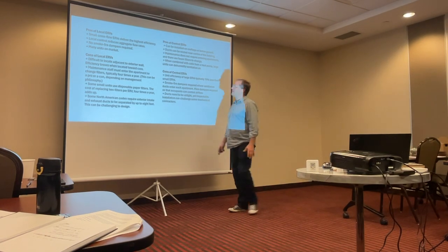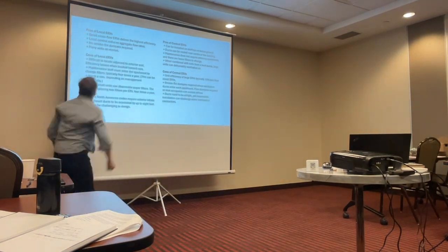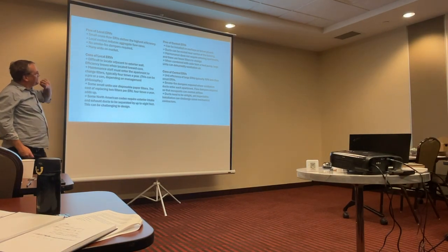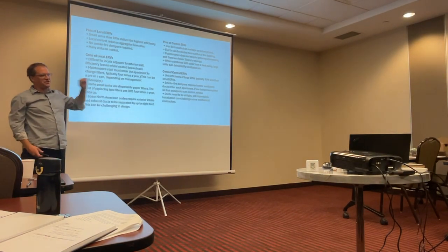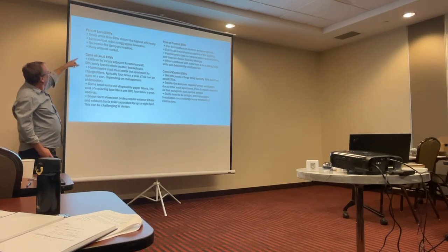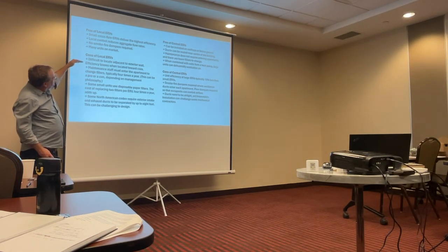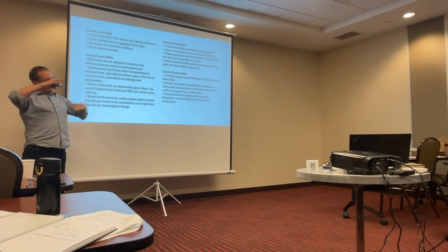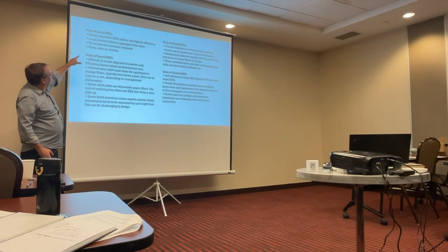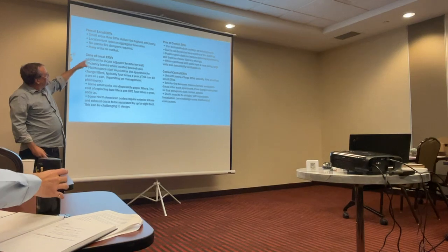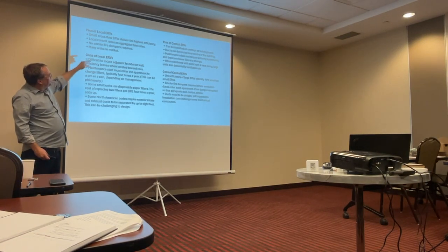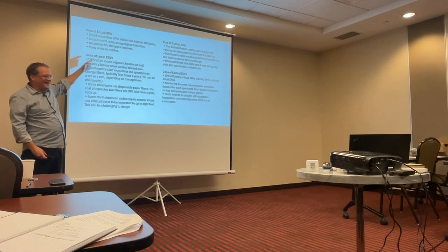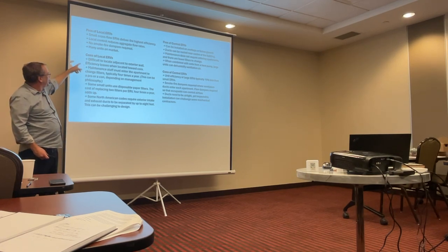Summary? Okay, really simple. Okay. Why I love local ERVs. The small cross-flow systems have the highest efficiency, and this efficiency is the cheapest way to pass certification on anything in the building. Small local controls reduce the aggregate flow rate of the whole building because you can manage each unit up and down, and they can go down a bit. And that improves performance. No smoke fire dampers required. In our market, smoke fire dampers are now around $3,000 a pair in the hallway. You can get an HRV for that. So it's a big cost and complication issue.